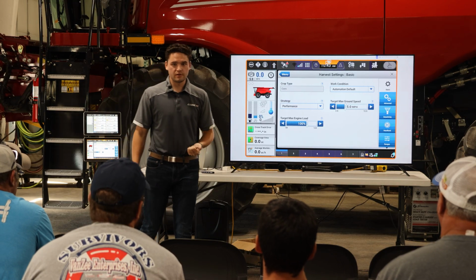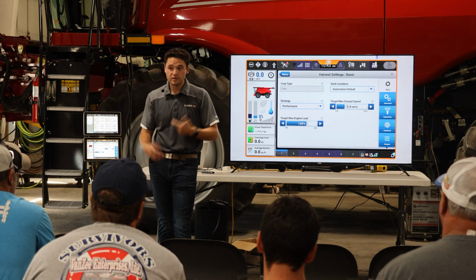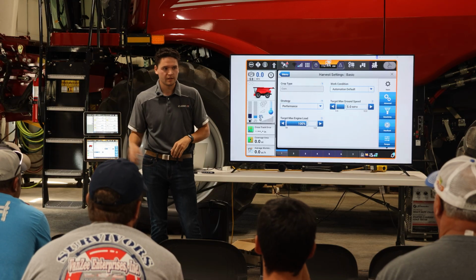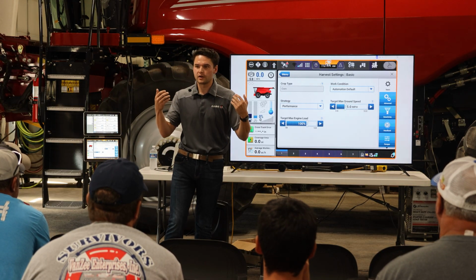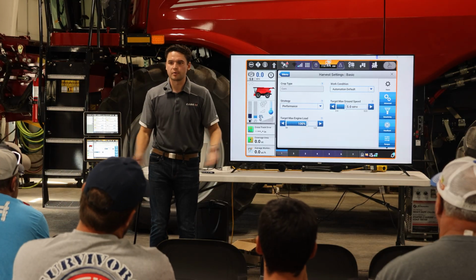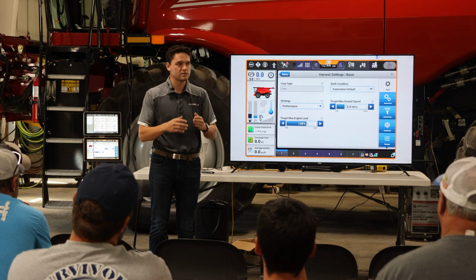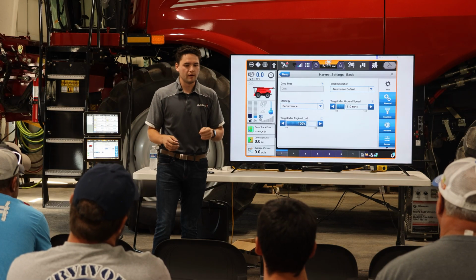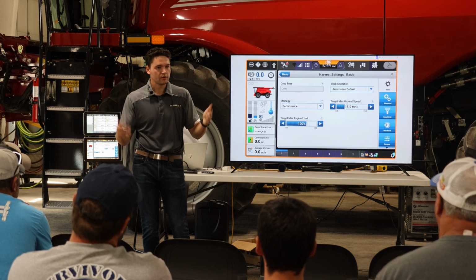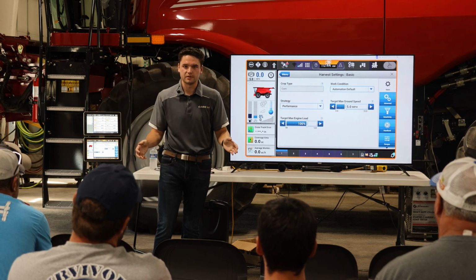So we're going to do our zero load cal. We're going to do this just simply by having our machine running, so threshing, feeding on, and header above max work height, stationary in the headland, and it's learning. This is what it looks like, no product in there. It happens automatically once those conditions are met, and engine RPM up. Once those conditions are met, it'll do it automatically without you having to do anything special.